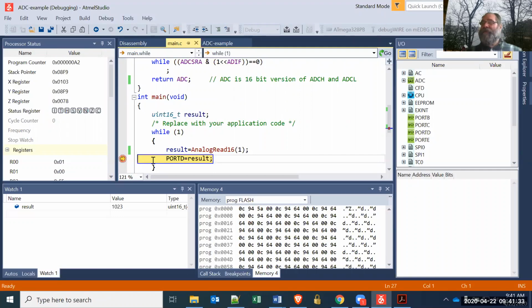If I was dealing with a temperature sensor, I'd probably want very fine resolution. If I was dealing with the brightness of an LED, probably 256 different possibilities is good enough. Even with some high-end graphics cards, you've got 8 bits for red, 8 bits for green, 8 bits for blue, which gives you better than 16 million colors. Really high-end graphics cards typically do, I guess, 10, 10, and 12 bits, I think, for the green, because your eye apparently can discern green a little better than red and blue. That gets you 32 bits total. But in general, 8 bits for a color is pretty good.